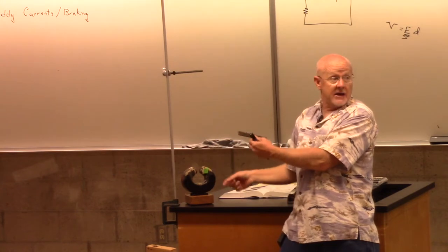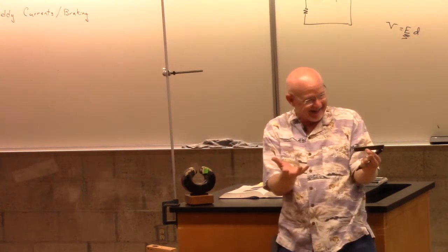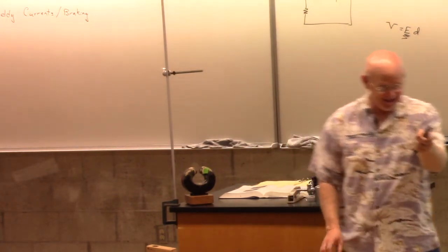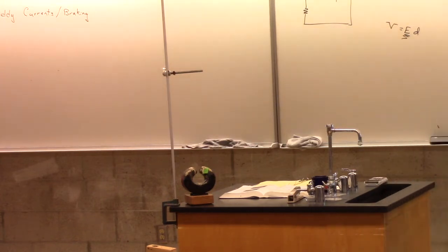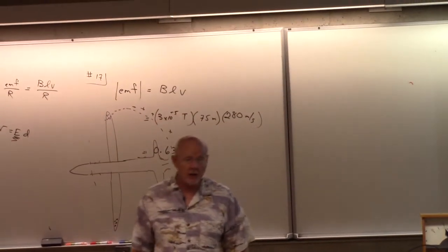So now they're attracted. But see, it's attracted as it's trying to exit, so that slows it down. So yes, things are reversed, but it's still a slowing down. So the current is reversed, the poles are reversed, all this in the secondary, but it's still a slowing down. And so whether it's entering or exiting, it's still a braking process, and it's still creating a current.